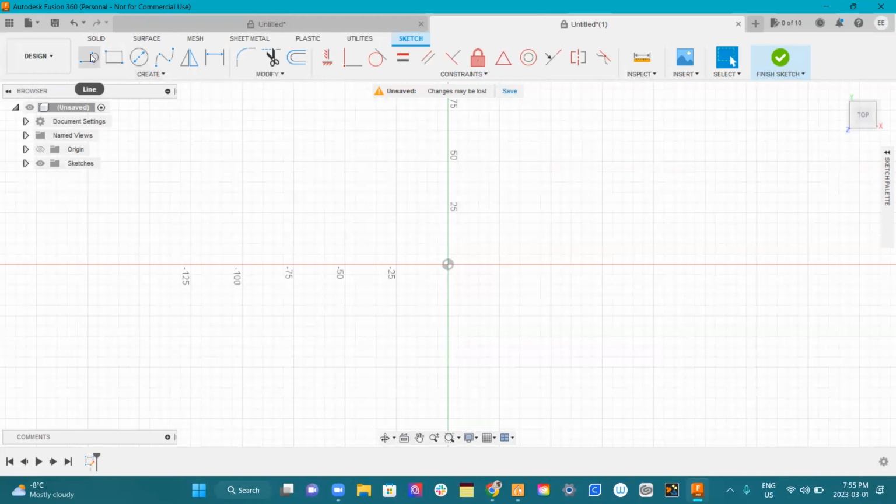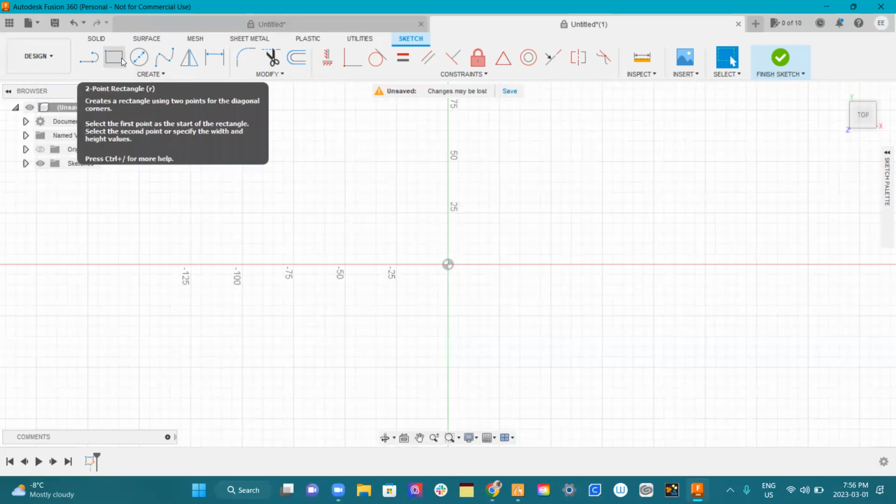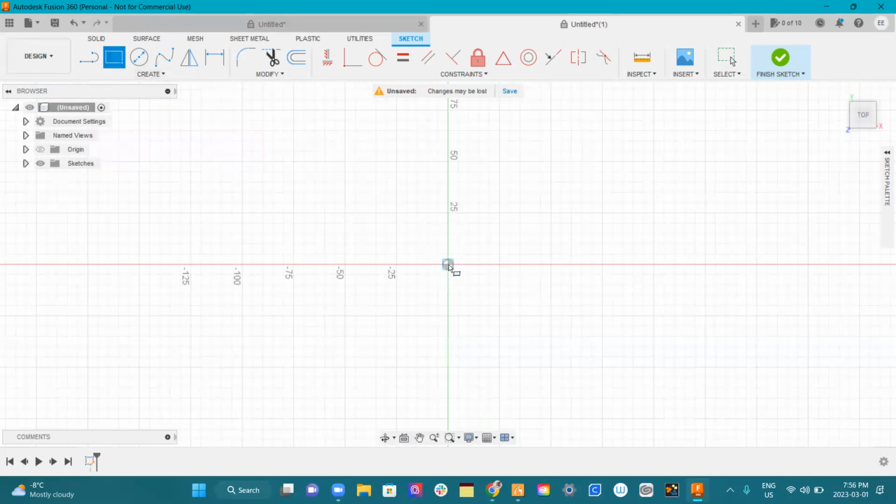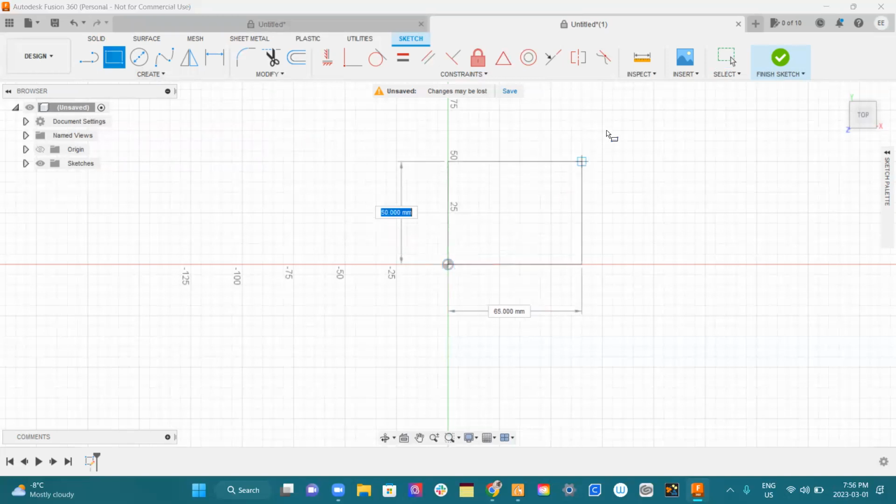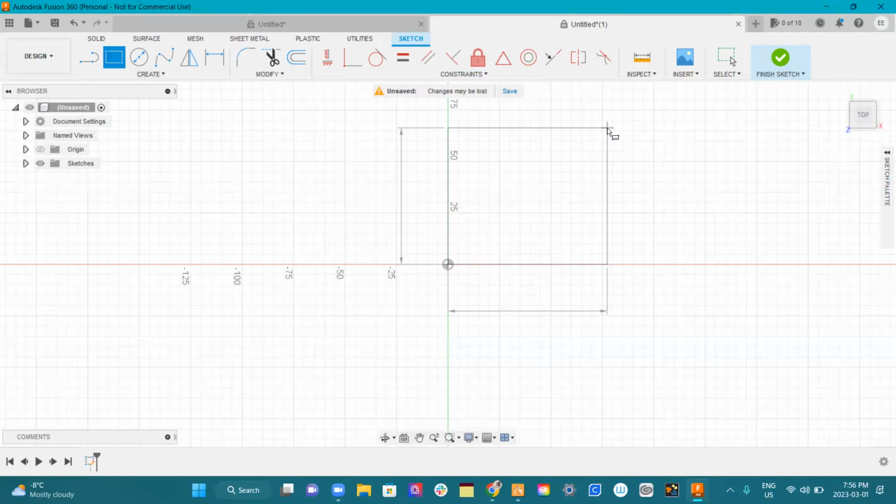So I clicked on the sketch icon and I select the flat thing that I'm going to do a sketch on. There are all these drawing tools that you can use, like make a rectangle. So I click on the center and I drag it out, and I've got a rectangle. And it's at a weird sort of dimension. It's 66 by 77 and whatever.